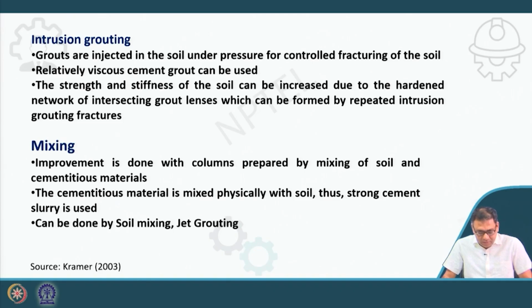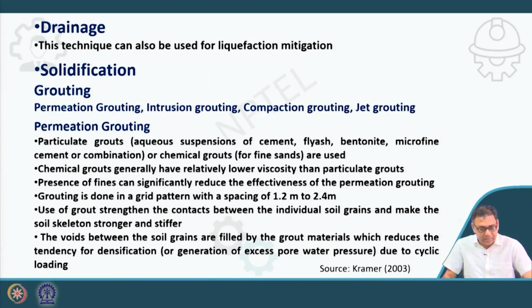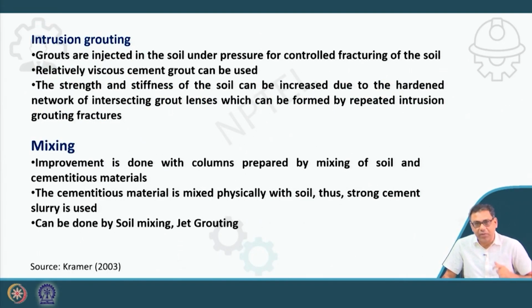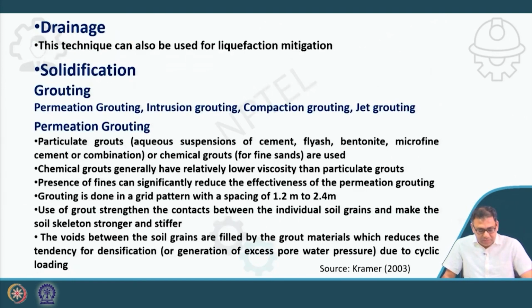It can be done by soil mixing or jet grouting. So that means jet grouting is also used for solidification, but it is in the form of mixing, where the soil column is being formed. So out of these four grouting techniques, permeation grouting, intrusion grouting and jet grouting are used for solidification purpose, and compaction grouting is used for densification purpose.